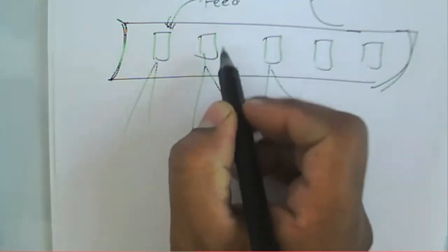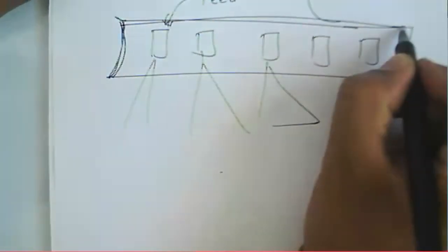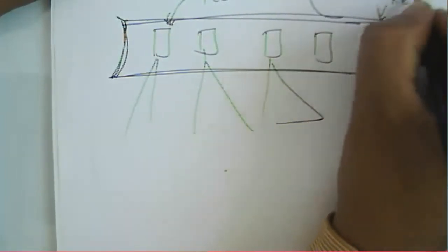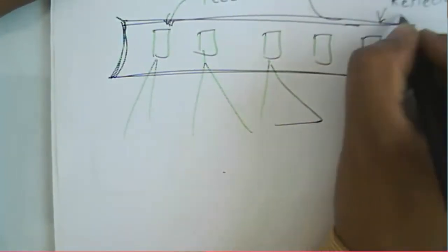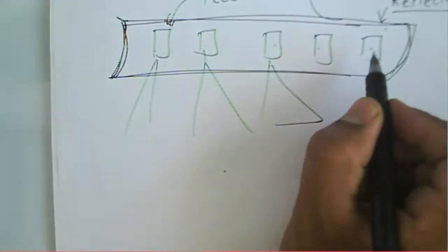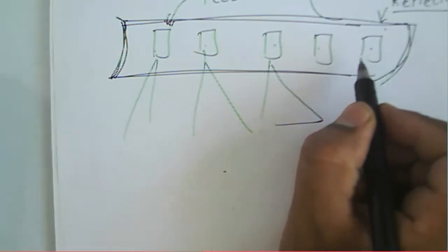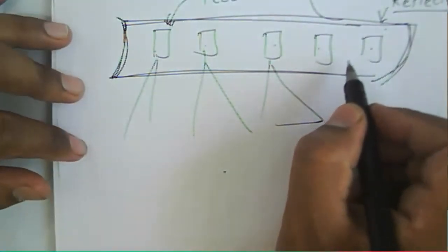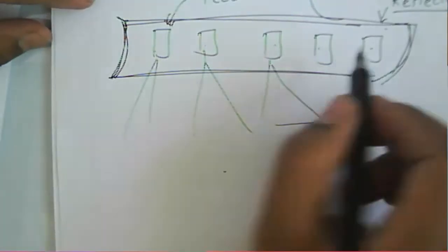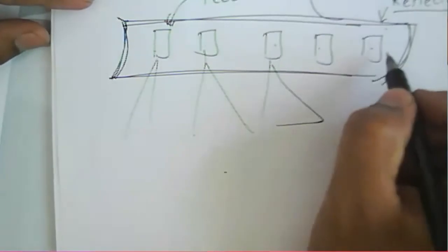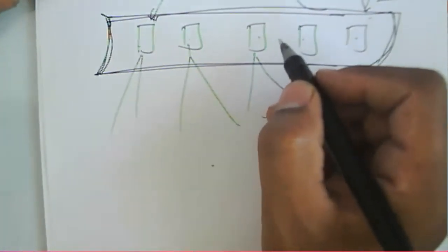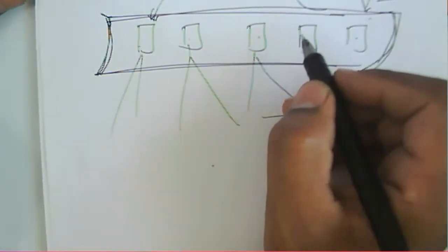because that reflector is a single reflector. We have the single reflector here, but using that single reflector we are using multiple dipole antennas. So using that we are getting multiple beams. It is the same antenna with the same reflector, but we are using multiple feeding elements. That's why we are getting multiple beams of that antenna.